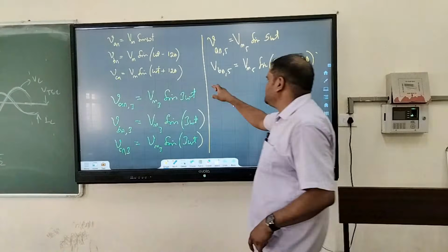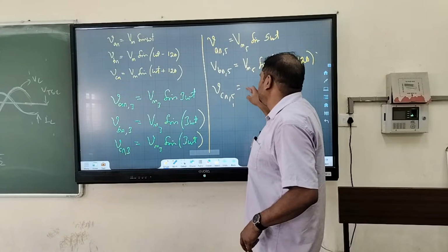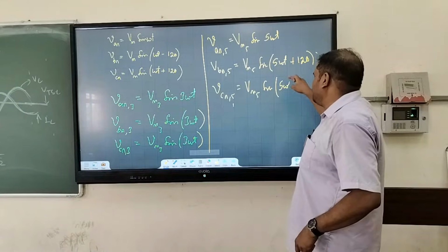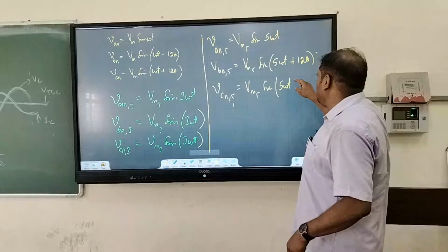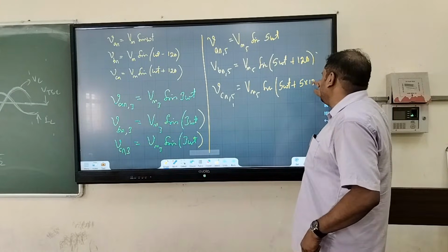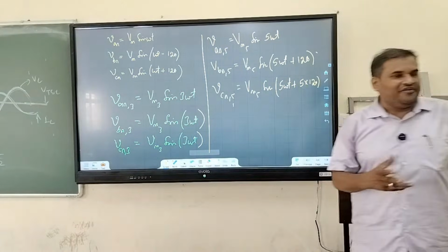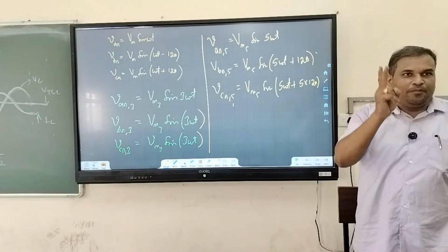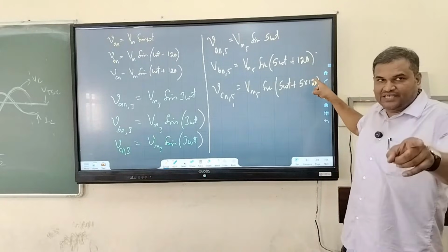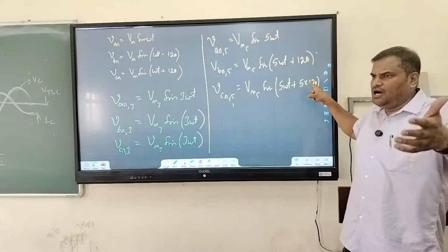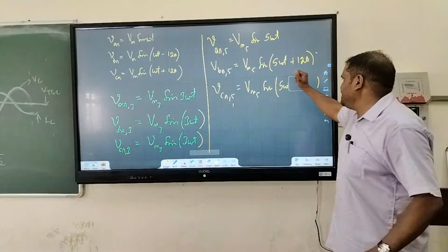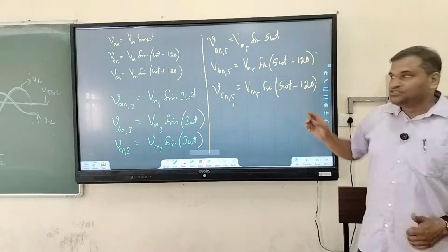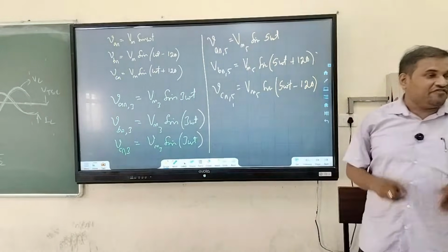Next, what is VCN5? VCN5 is equal to VM5 sine of 5 omega t plus 5 into 120. What is 5 into 120? 3 into 120 is gone, and 2 into 120 is 240. So plus 240, or equivalently minus 120. So we can write it as 5 omega t minus 120. So here we are getting VAN5, VBN5, VCN5.